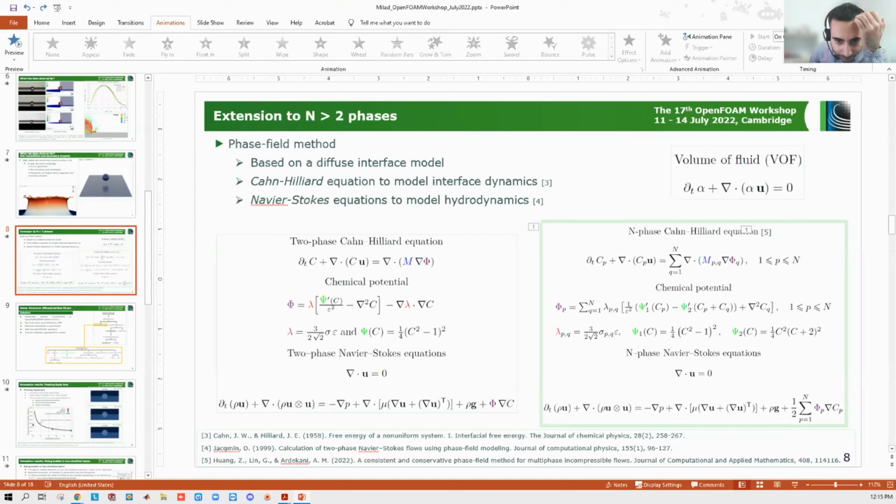There are some questions in the chat. The last one is, why not use VOF? Well, we would like to move toward miscible simulations, and for miscibility we need a lot of physics, and a lot of natural physics is happening at the interface. In volume of fluid simulations of this type, you normally add an arbitrary diffusion term on the right-hand side, but we want it to be predictive and physics-based. So there should be an interfacial region so that we can work with it.